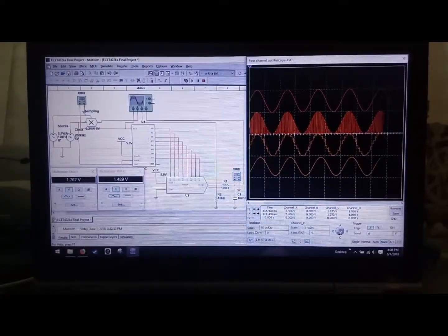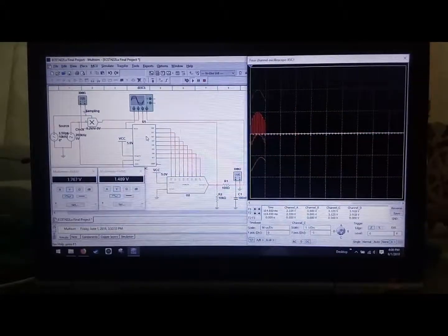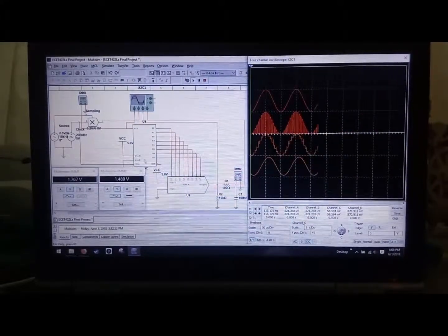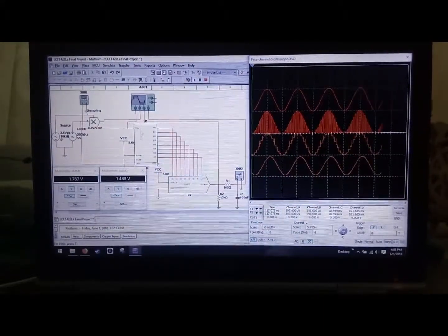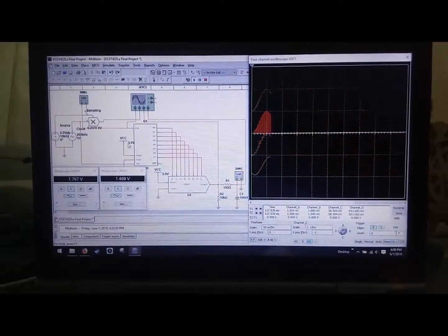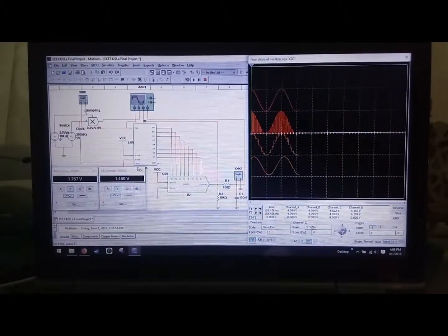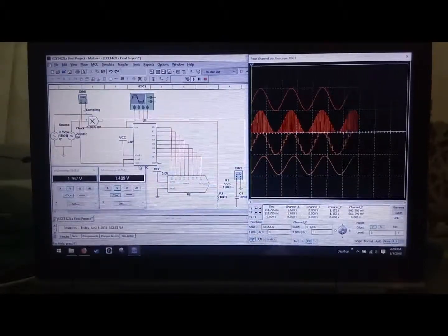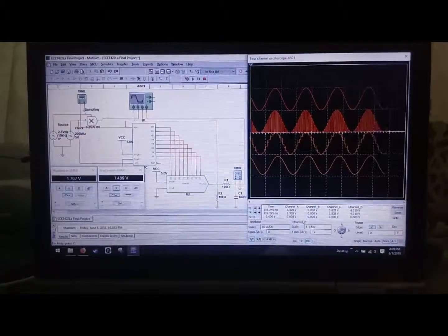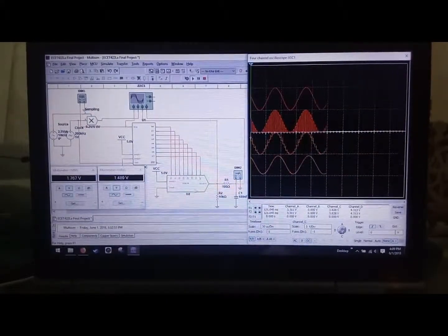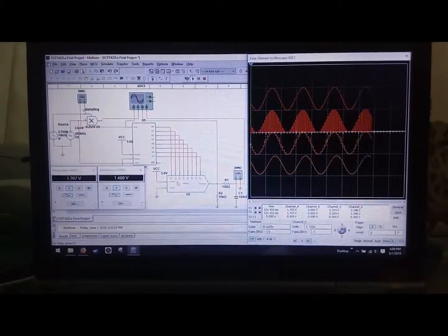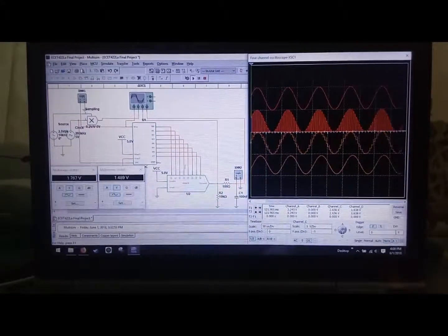The next part of the circuit is the analog to digital conversion. In this type of circuit, we use an ADC IC wherein you just input the source signal to the Vin, the Vref positive to VCC, the Vref negative to ground, and the SOC, or the start of conversion, to our clock. And then each of our digital values, we connect to its respective D0, D1, D2 of our digital to analog converter.